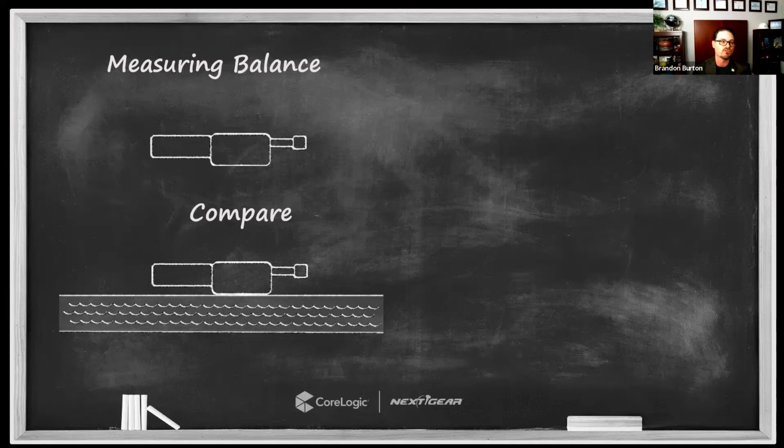This comparison between the 2 helps you understand the space balance. How well have you installed air movement to put your dry air in contact with the wet drying surface, all right? Now, this is the simplest version of this. When we're dealing with more complex assemblies with multiple layers and air gaps and interstitial cavities, that hygrometer you see on bottom should actually be measuring the air in the interstitial cavity, right? Inside the wall cavity, or the air coming out of your system that's drawing air out from underneath a flooring material, for example, right? That's the air that I would measure in that case.